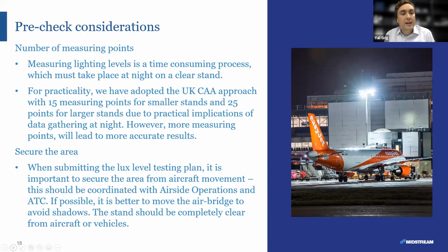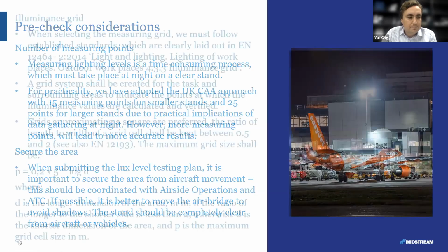The second point is we have to secure the area. Okay, so we mustn't be in a position where we're measuring and an aircraft is coming to disembark on that stand, or vehicles are coming along, or there's an air bridge. So, when submitting a lux level testing plan, we have to get that coordinated with airside operations and also the ATC, right? It's better, if possible, to move the air bridge out to avoid the shadows, and the stand should be completely clear from aircraft or vehicles. So some coordination is really required with ops and ATC.